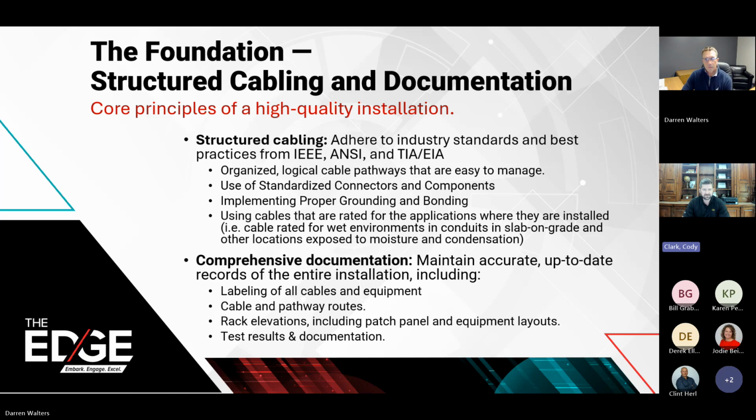Implementing or using standardized connectors and components simplifies the system, adding and adjusting your electronics inside of it. Implementing proper grounding and bonding. This is an important one because of avoiding potential damage to your equipment, but it also impacts the performance whenever the trays and items and shielding are not properly grounded and bonded. And then using cables properly rated for the applications they're installed in.